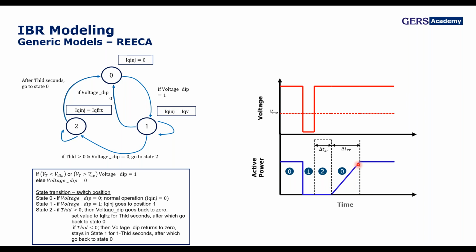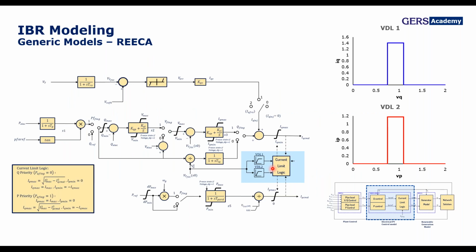That caused some issues in California, since that created an additional time for the momentary cessation that will be described with the next characteristic. The momentary cessation is represented with this block here. What is momentary cessation? Momentary cessation is an inverter operating state where the power electronics, I mean the firing commands, are blocked such that both the active current and reactive current go to 0. Sometimes only the active current goes to 0, some others both of them.